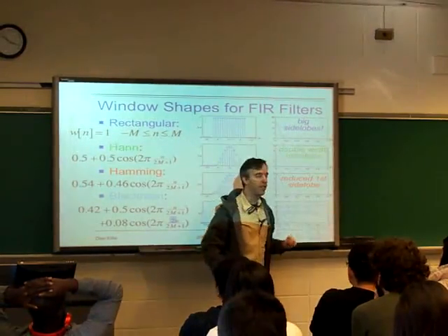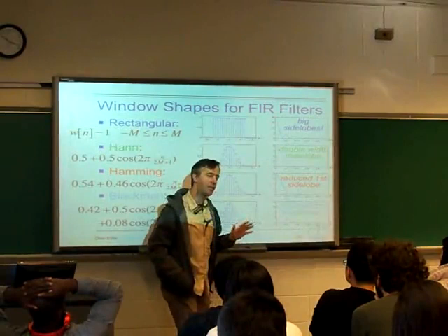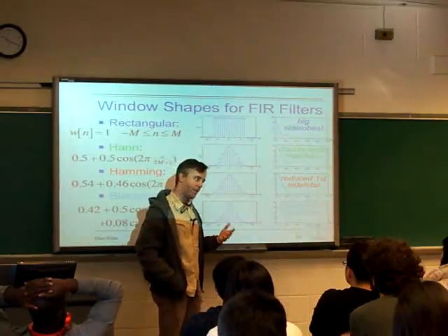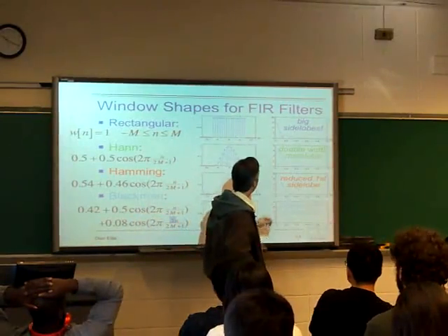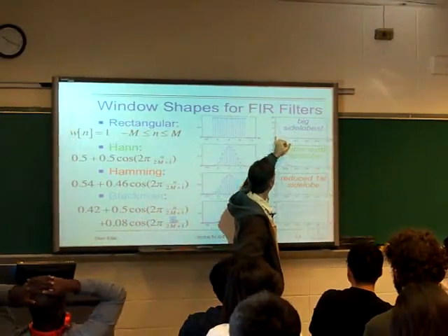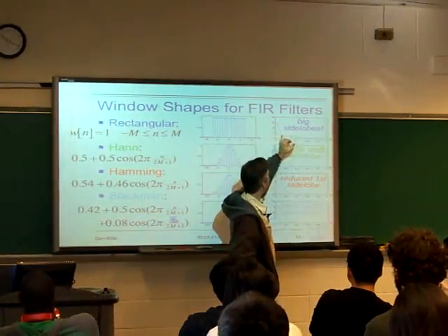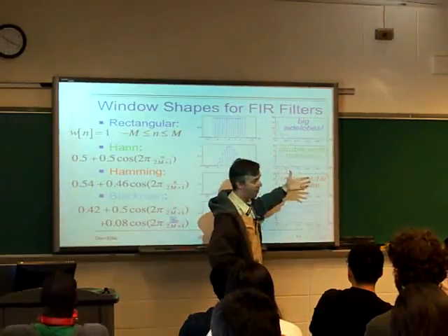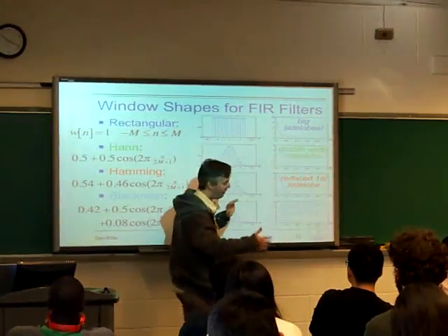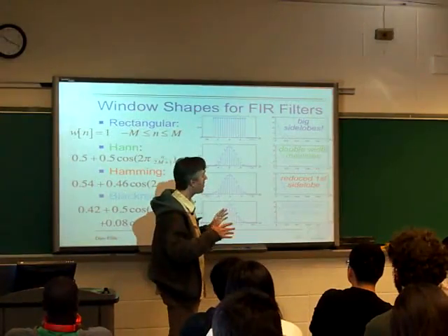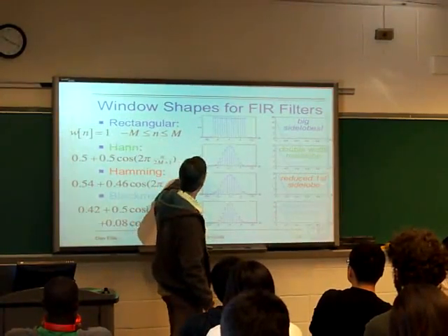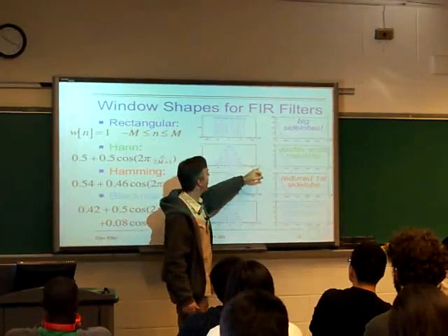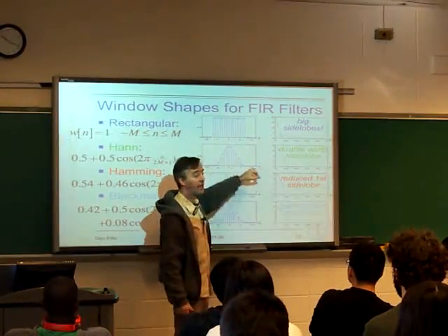Now, to shift it in frequency means multiplying by a sinusoid, right? Shift in frequency is just modulation. And shifting it so that it lined up here would be shifting it by 1/n of the frequency range, where n was the length of the window, which is actually multiplying it by the cosine that finishes 1 cycle in the length of the window.